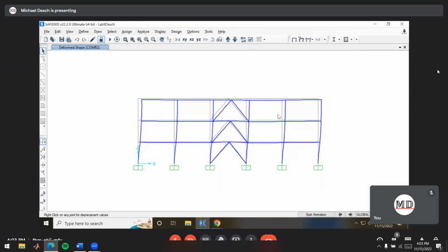And now we can get a bit more of a sense of how much it's deforming. The reason it gave us a really small exaggeration is because it's moving laterally much less than those girders are deflecting downwards out of view here. So it's basing its automatic scaling on their deformation because it's the most deformed part of the system.